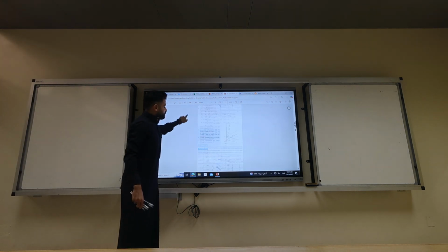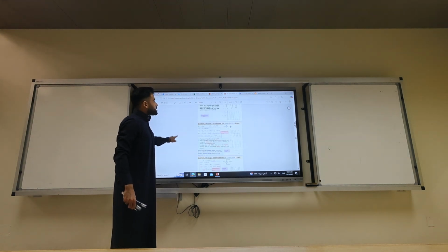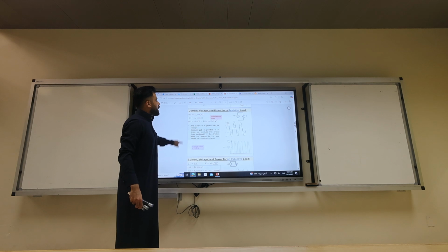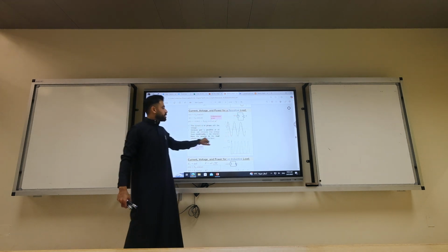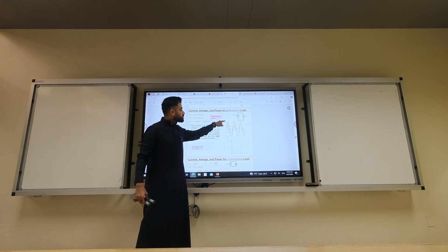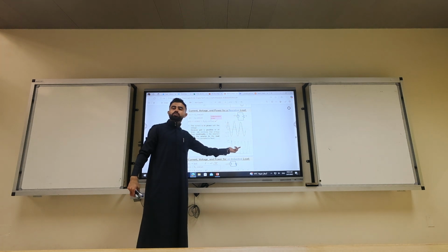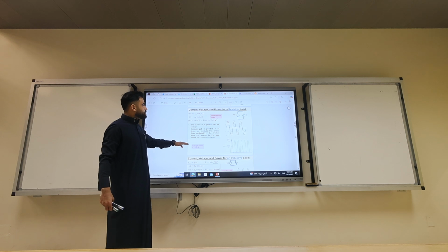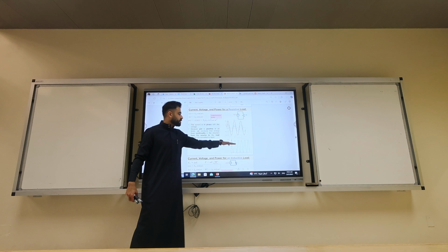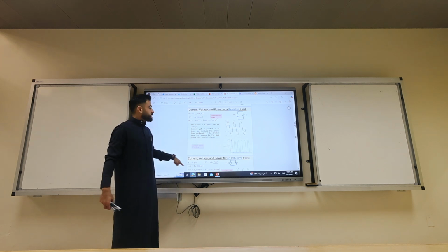So last time, we talked about the concept that if you have a resistive load, you will have only real power that is in phase with the V and I, but at twice the frequency. Its average value is positive, which is Vm Im over 2, and it takes the form of dissipating heat.